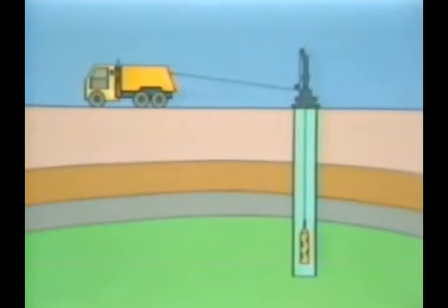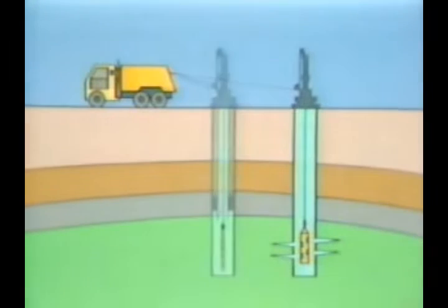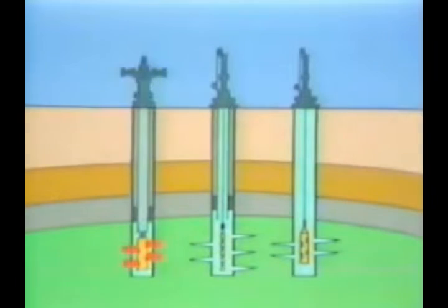Cased holes may be perforated in several ways. Using conventional casing guns run into the well on electric wireline through wireline pressure control equipment. Using through tubing guns run into the well after the tubing has been installed. Or using tubing conveyed perforating guns run on the bottom of the tubing string and detonated using mechanical, electrical, or pressure-activated firing mechanisms.